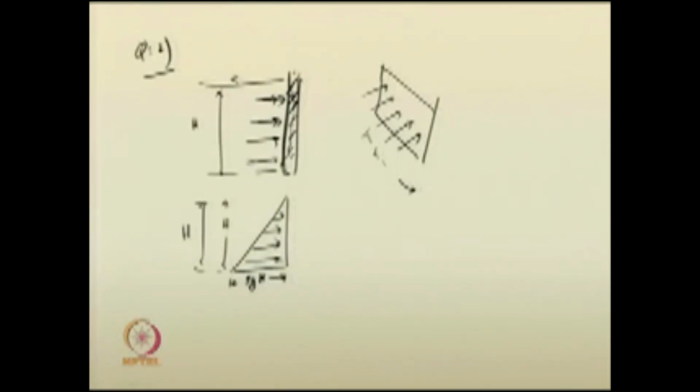So, this triangular area, you know that will give you the pressure into the area of this sluice gate, that will give you the pressure force. So, your sluice gate has to be strong enough to resist that force action from water, and it has to be sufficiently strong. So, therefore, it has to consider the pressure. Thank you.